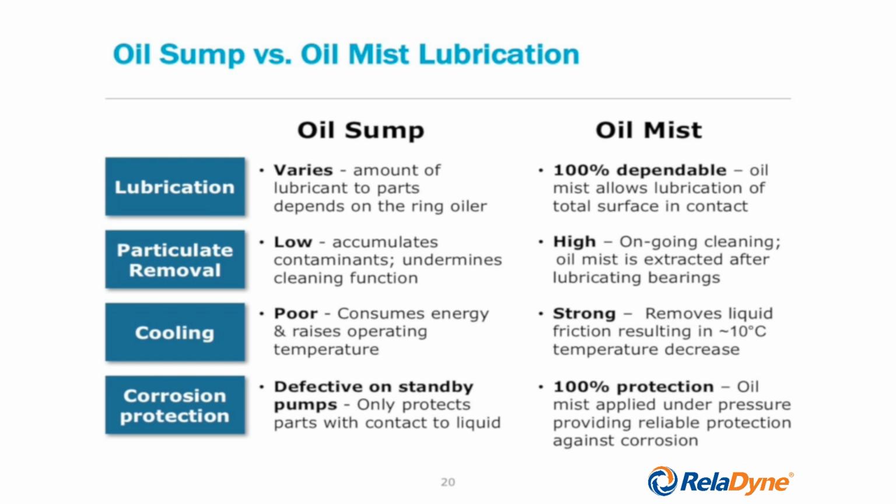And as we now have a piece of machinery not even operating, in the daylight or in the sunlight, I might say, we have a bearing housing that warms up. And as a result, the air inside that bearing housing expands and it gets expelled. And then at night, even with the equipment not running, you have a cooling effect because the ambient air is cooler.